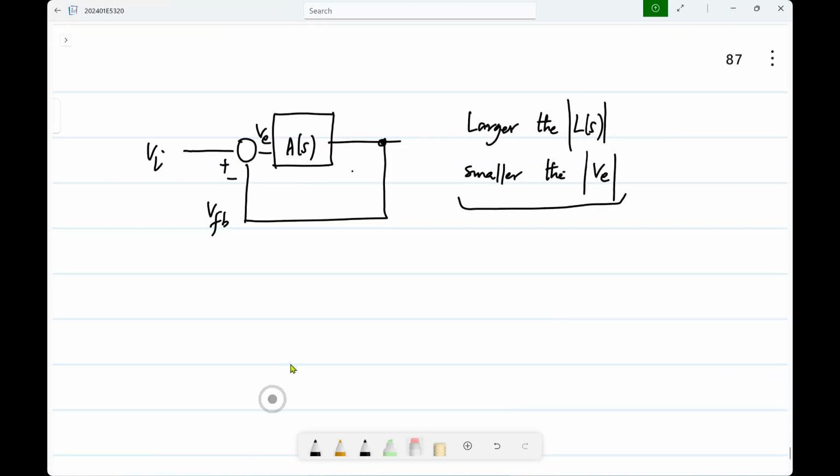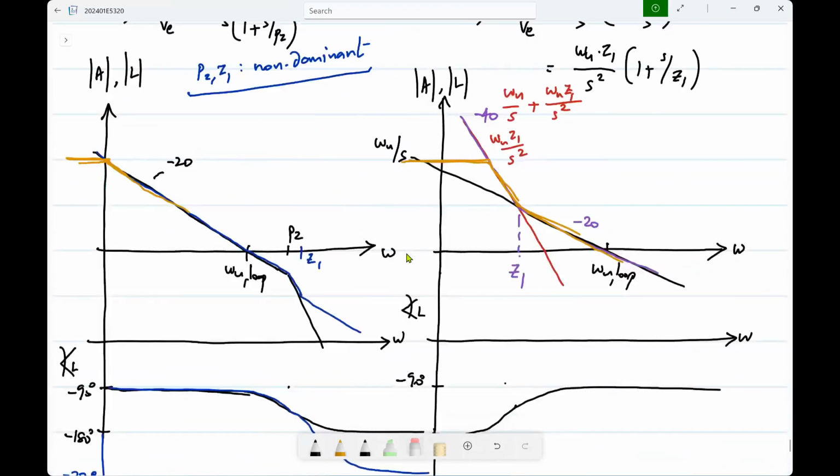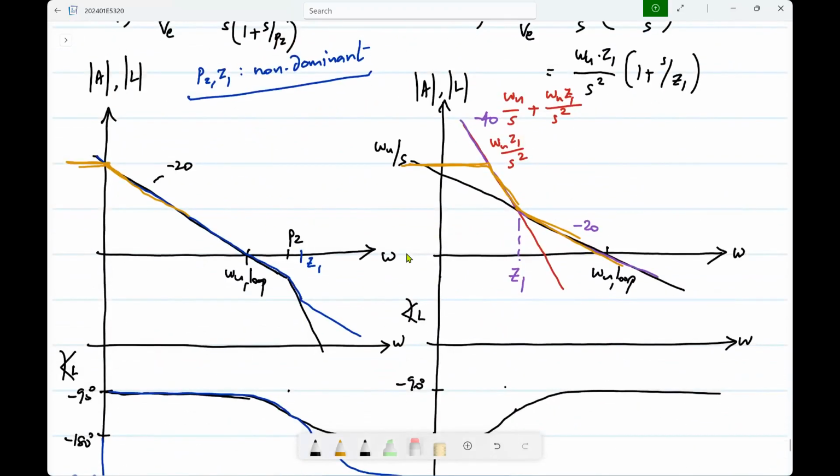So this feed forward op amp provides a higher loop gain in some range of frequencies. Now, if you have a third order op amp, that is a 3-stage op amp, in the Miller compensated op amp, it will still show a first order, dominant pole behavior, but it will have a higher DC gain.